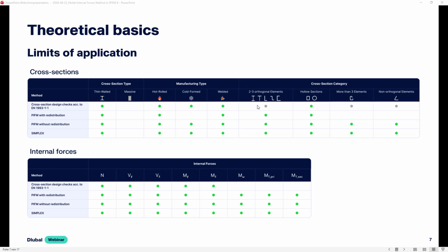And that's not what we want to consider now, because we want to do an economical design check, which would mean that we have to do a plastic design. And the methods that are given by the Eurocode would be relatively conservative in this case.